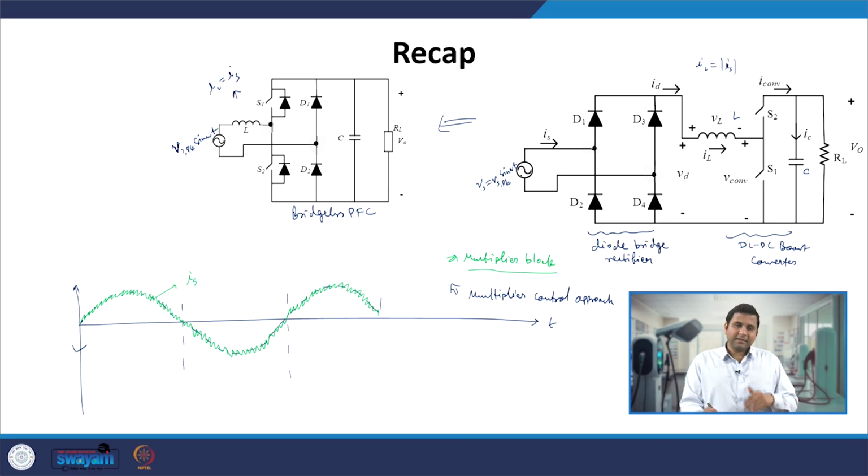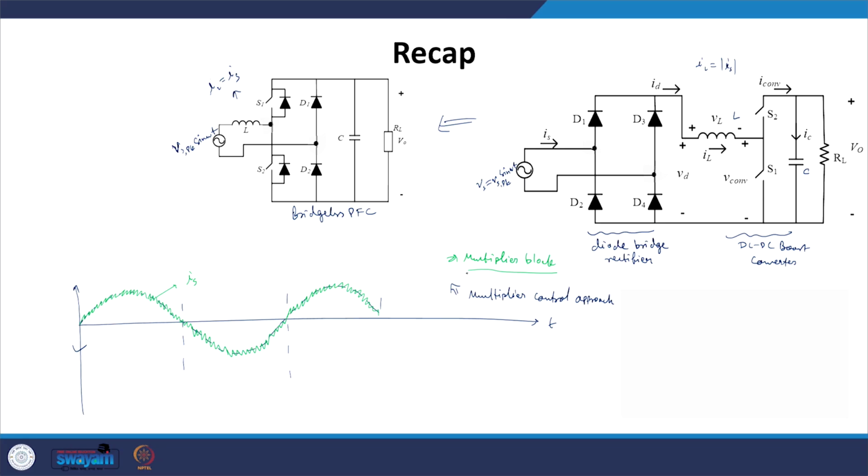And we know that generally the grid voltages have variation in frequency, and also variation in voltages. Obviously those are maintained within the tolerances, but there is a variation. We cannot say that at every time it is a pure sine wave having Vs peak in the positive direction and minus Vs peak in the negative direction. So we are not able to sense the exact peak, and we cannot say that the entire frequency is actually the nominal frequency.